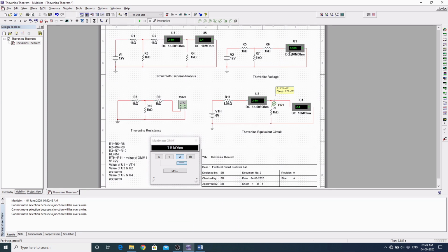One thing I would like to say is that you will see 5.999 volt is available over here just because of this R6. As I had already told, the leakage current will flow through R6, and that is happening. So a minimum voltage drop, that is 0.001 volt, has occurred over here, and due to that it is showing 5.999 volt. For our calculation, we had ignored that one, and in the practical case, we will also get some voltage deviations from the 6 volt level.